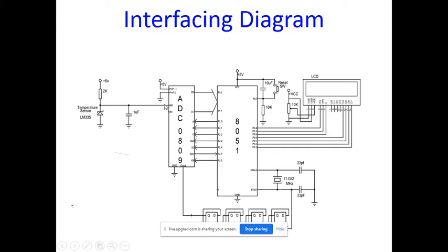And just now I want to take input from channel number 0, and that's why I'm writing 000 here. Then initially the value of address latch enable is low. When you want to latch, it goes from low to high, a pulse, meaning a rising edge. Then your controller will send start of conversion, an input given by the controller, to start the conversion. Then the ADC 0809 will start the conversion.